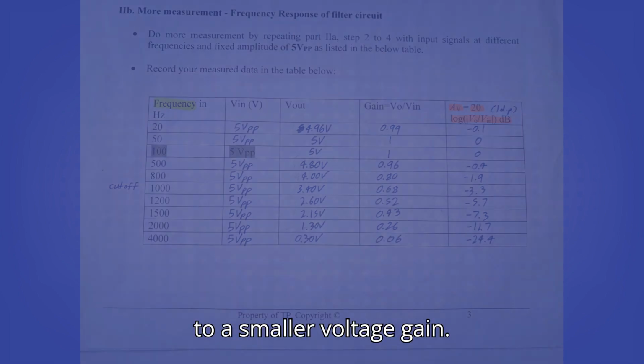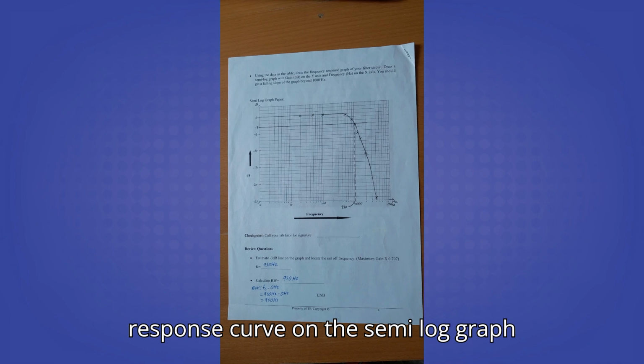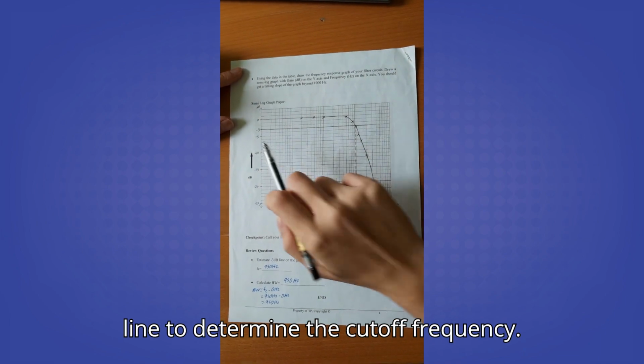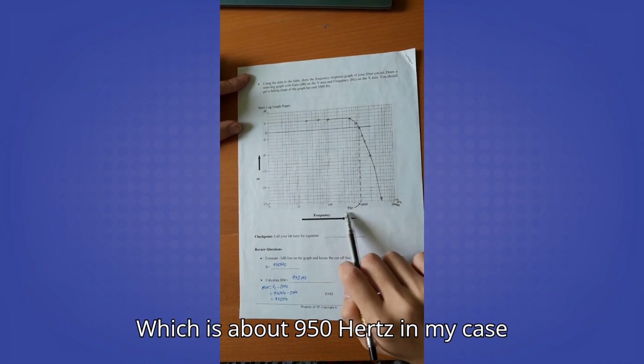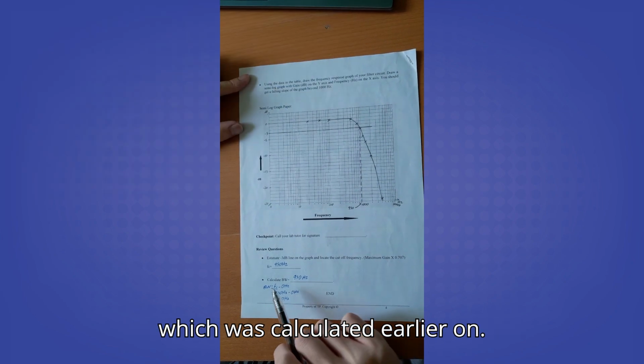Using the data to plot the frequency response curve on the semi-log graph paper, we can draw a -3 decibel line to determine the cutoff frequency, which is about 950 Hz in my case, and is close to the expected bandwidth, which was calculated earlier on.